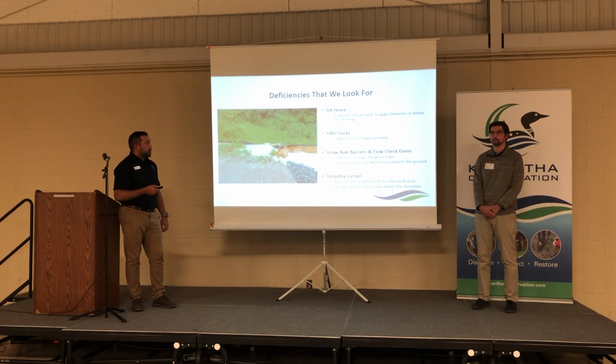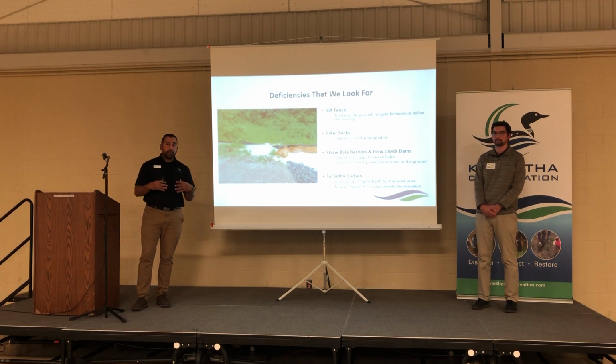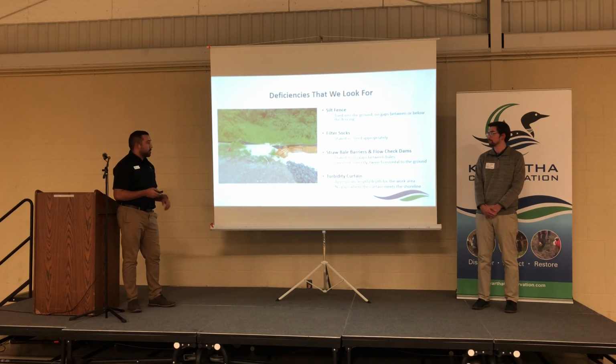Filter socks, we'll check to make sure that they're staked in and sized appropriately, depending on the application as well. Sometimes we find that they are stacked to create a taller barrier. We'll check for gaps to make sure there's no silt traveling around and that it is being properly filtered through.